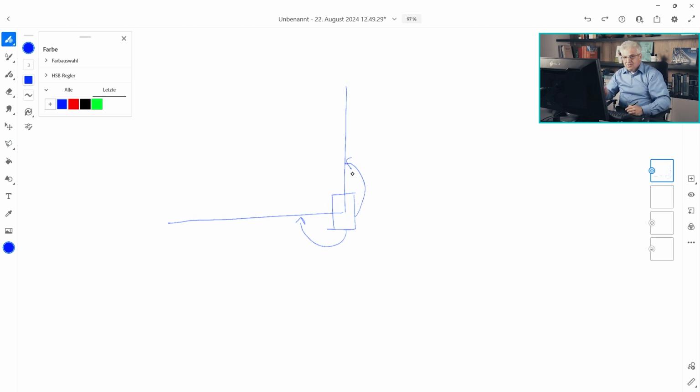So therefore, during this connection of the 1D members to ribs, deactivate the walls, leave on your screen only the plates and the 1D members, and then connect nodes and edges only for these selected members.